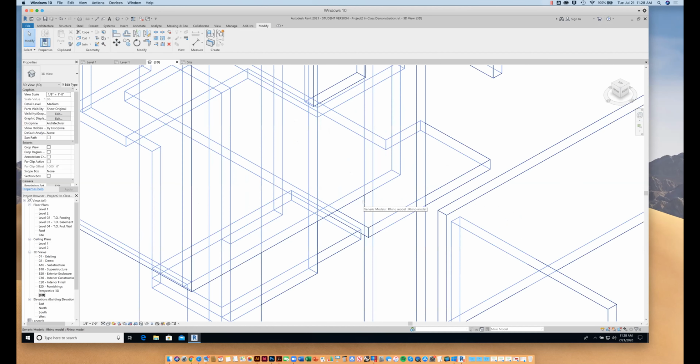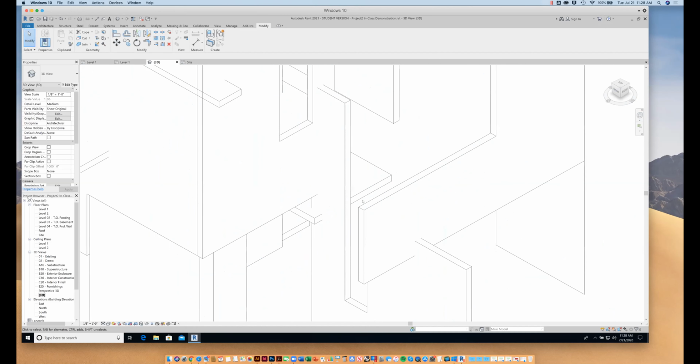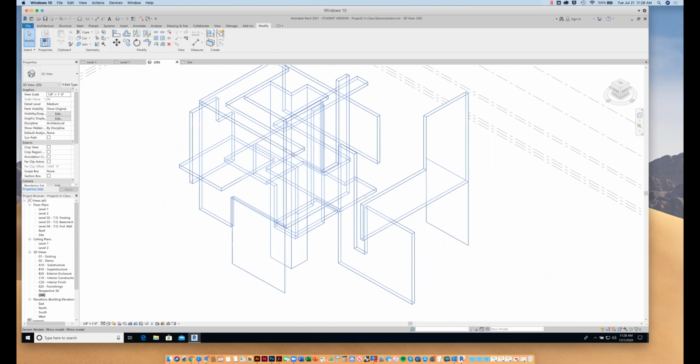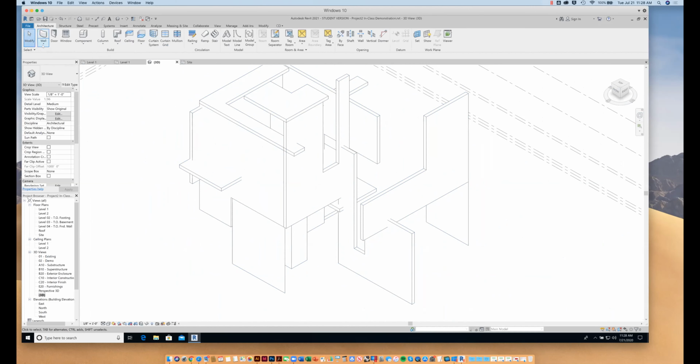Okay. So what you can see is that it took all the objects in our Rhino model, and now they're just one big generic object. Okay. And so what we're going to do is start to classify these things as different pieces of geometry. So I'm going to go to the architecture tab, and you can see that there's a whole raft of tools here. The one we'll be primarily focused on is wall. So we'll start to make certain pieces of geometry walls. We'll also make some curtain systems. And then inside of walls, once we make walls, we'll actually start to add wall reveals, okay?